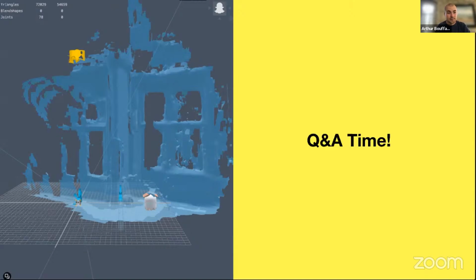If that statue is made out of any glossy material, that's also something you might want to avoid. So a little trick that you can do, which I've done in the past, is that you can actually scan as a mesh the area around that shiny object, and it also applies to really big buildings. And then if you're really motivated, you can do a photogrammetry scan of that building and recreate it as an occluder. So make it in Blender and go full out, remake the entire structure more or less, and use that as an occluder instead of the mesh. And for large buildings, that might be very useful.